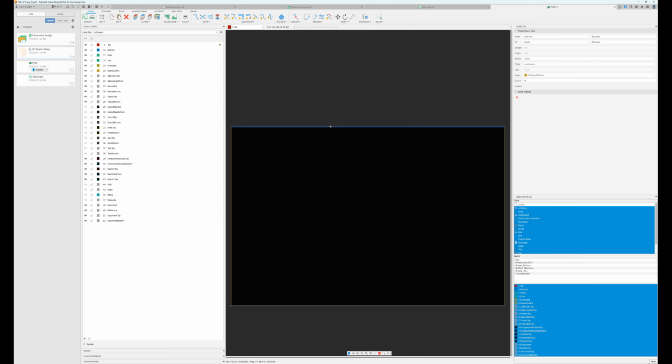And then we got to do the length, so you click up here, and from 0 to here, and then you got the bottom one here, and from 100 to 0, and it actually should be like 0 to 100, but anyway, so you click here, and so it's 63.5, and we want it to be 96.5 long.